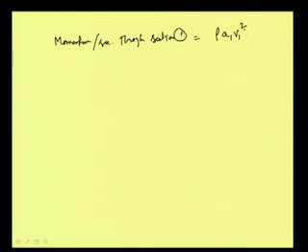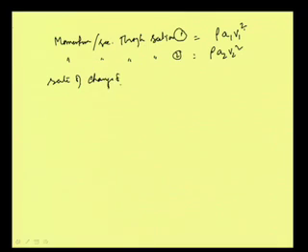So, this is the momentum passing through section 1 per second. Then the momentum per second through section 2 is equal to rho A2 V2 square. Then the rate of change of momentum, we are coming to Newton's equation now, we can write as rho times A2 V2 square minus A1 V1 square. So, this is the change in momentum, which should be equal to the applied force. So, from Newton's equation, what can we write?